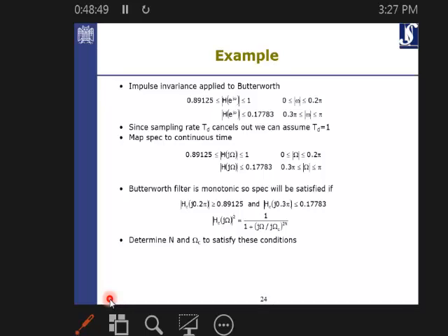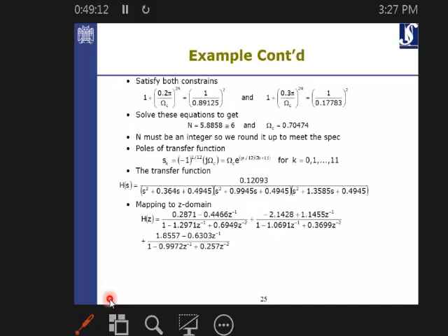So knowing that, what we try to do is just go into the analog equivalent of that. You use, for example, one of the methods here. You use the Butterworth filter, and using these margins, try to figure out how much N you should have. So we figure out the best N, putting all those margins. This constraint should be satisfied at the same time.